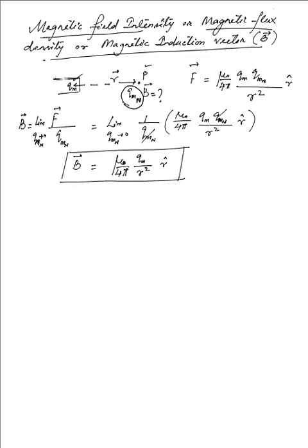Now, why do we use the term magnetic flux density? Remember, in case of magnetic flux, just like the case of electric flux, the magnetic flux can simply be denoted by phi. It is simply equal to the number of magnetic lines of force linked with a given surface area. So the magnetic flux is B dot A, the dot product of B and A. So this is simply equal to BA cos theta. BA cos theta is the magnetic flux, and why then do we have the name magnetic flux density?